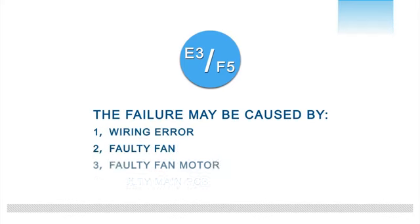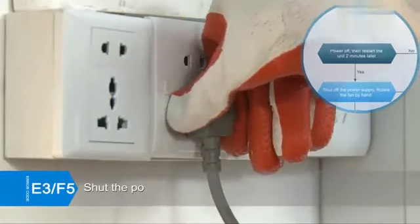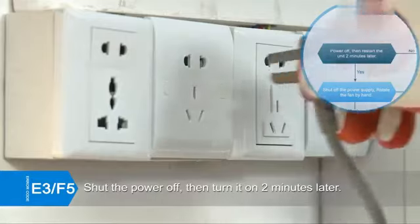The failure may be caused by: 1. Wiring error. 2. Faulty fan. 3. Faulty fan motor. 4. Faulty main PCB board. Shut the power off, then turn it on 2 minutes later.